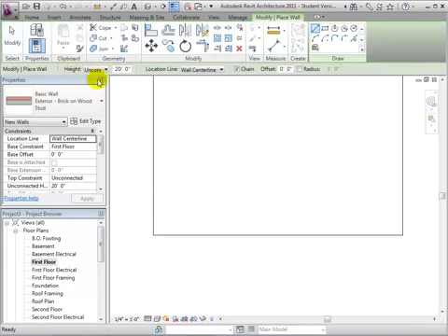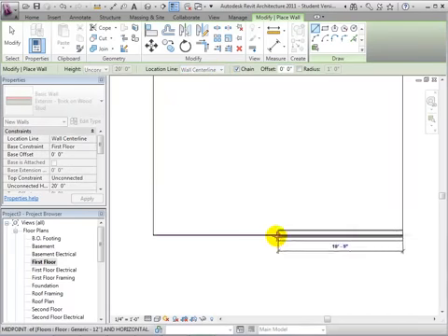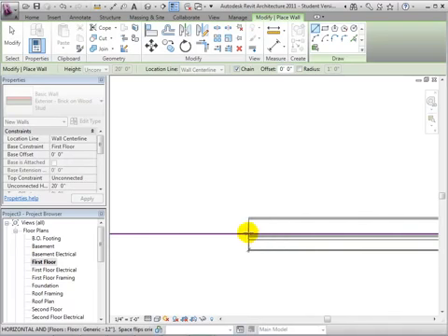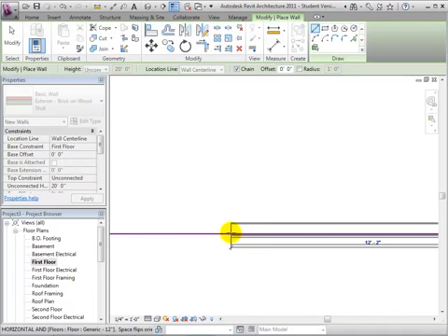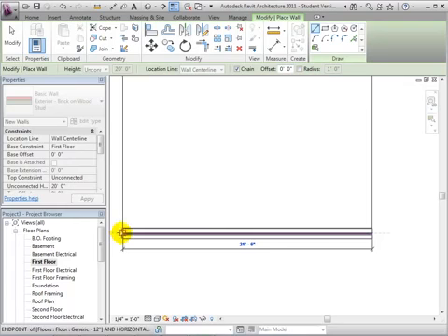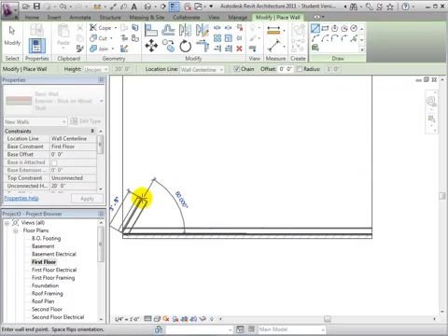Walls are placed using the location line as a reference. This option chooses which part of the wall will be placed over the line we draw. As you can see, as we create this wall on the edge of the slab, we are drawing where we want the wall center line to be, since this is our location line.